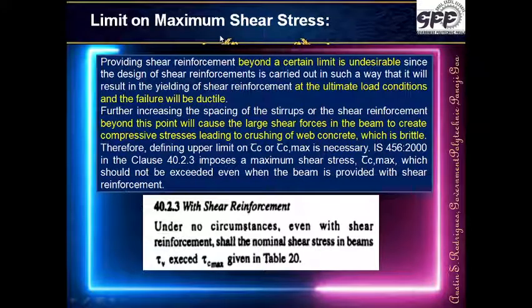Now there is also a limit on maximum shear stress. What is this limit on maximum shear stress? We know that beyond a certain limit, providing shear reinforcement is undesirable. Let us understand one thing: we always want to do a ductile design.